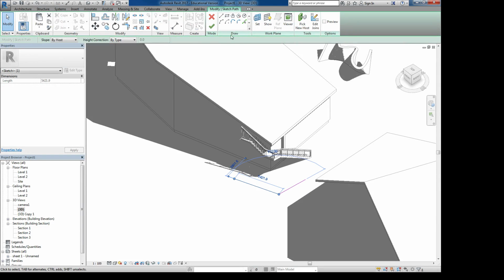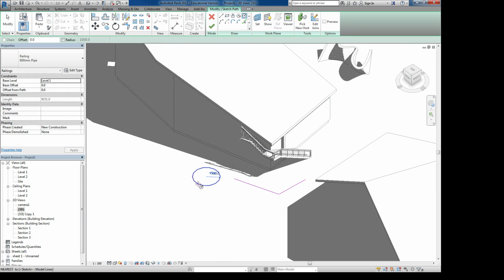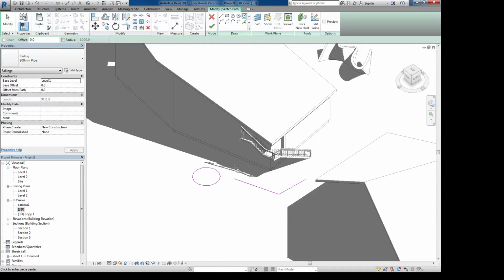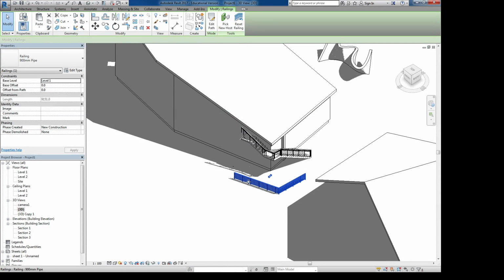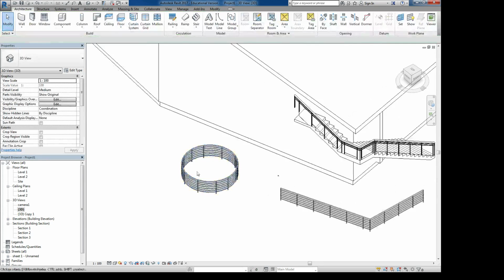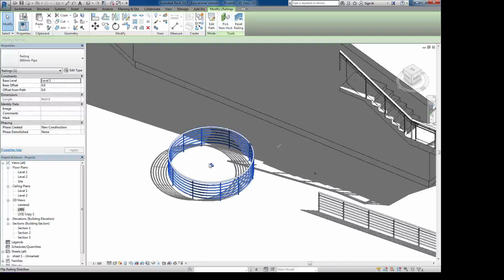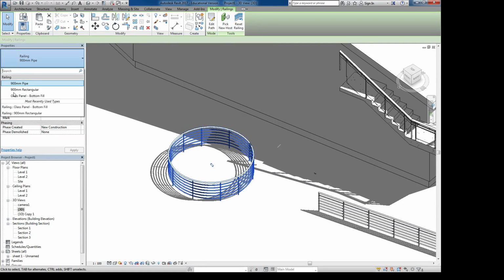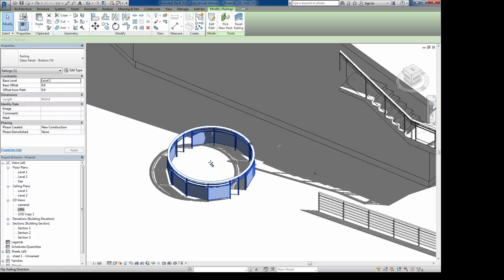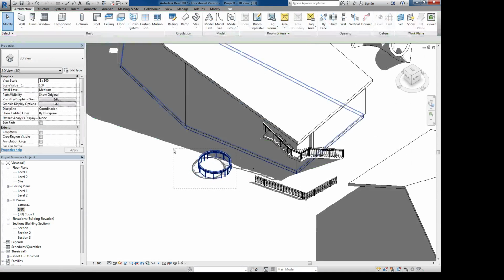If you edit this and if you do a new shape over here, because it's not connected, it will give you an error. So if you want to do two different railings that are not connected, you need to actually draw two different railings. So I'll just copy this over here, edit that, delete this, draw this over. Now it's gonna work. Similar to walls and windows, you have this arrow that shows the interior and exterior. If because of the type of the railing you're using, the exterior and interior were different, using this you can switch between. And that's all about stairs, ramps, and railings.